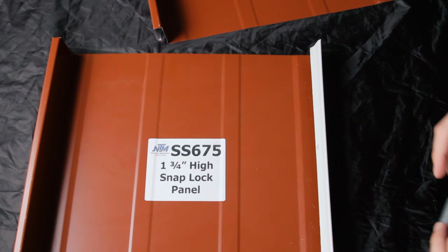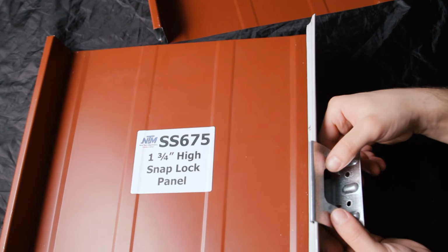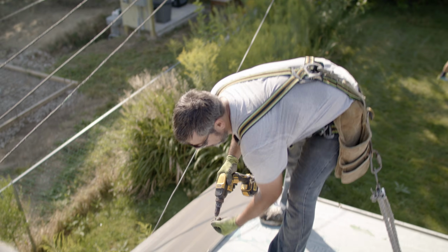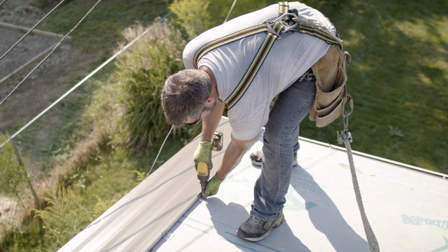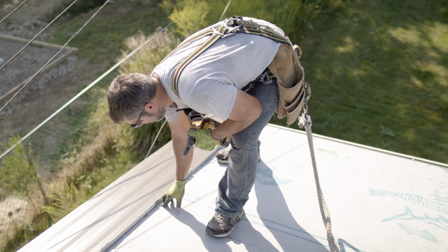Standing seam metal roofs use some of the same accessories, such as underlayment, tape and gun caulk sealant, and rubber pipe boots. But a unique item for most standing seam assemblies is a clip. Clips hook onto one side of the panel and are fastened to the roof using screws, which are then hidden by the next panel on the roof, thus making it a hidden fastener system.